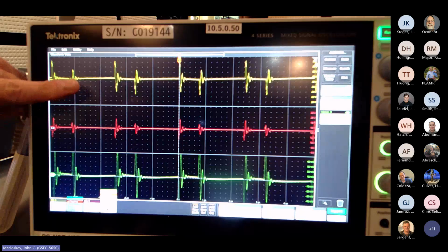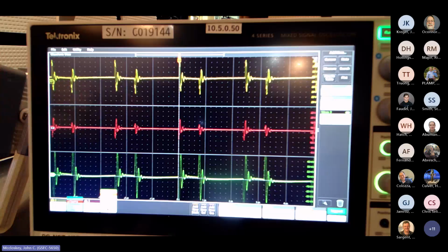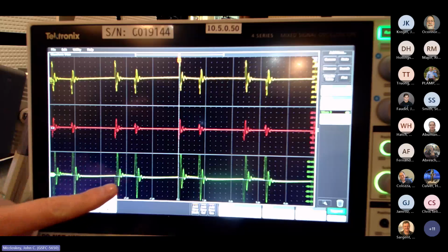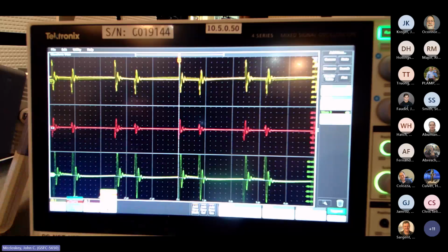So you can see that there's a bit of wobble on the yellow trace. That's our primary power input. But not much is getting through on the secondary or on our current probe yet. It's just unfortunate that we've got these nasty switching transients here that are minimizing our ability to see the ripple current that we're deliberately injecting. But once it comes up, you can definitely see it.